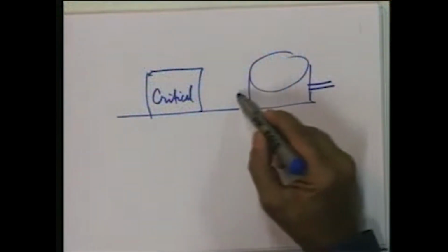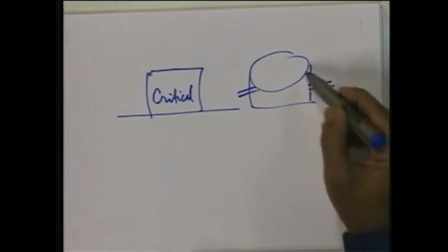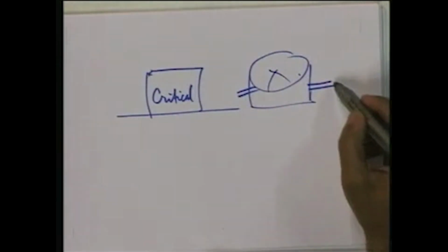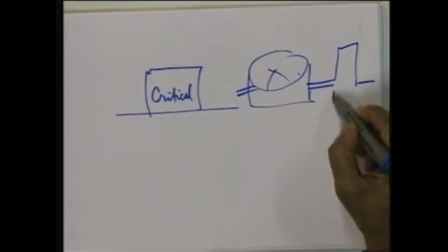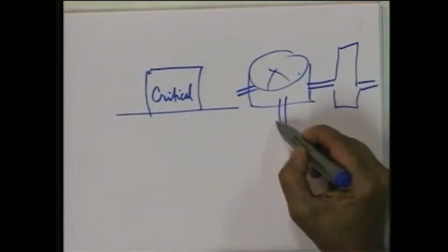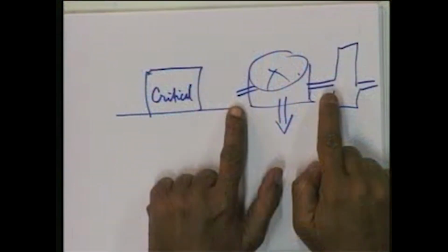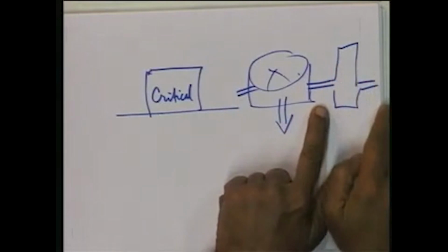These usually have pipelines serving as inlets and outlets which are connected to them. Imagine a tank like this connected to a number of other systems through pipelines undergoing consolidation. If this undergoes consolidation during its lifetime, and if that consolidation is significant, then imagine the effect on these pipelines and the effect of these on the adjoining structures.